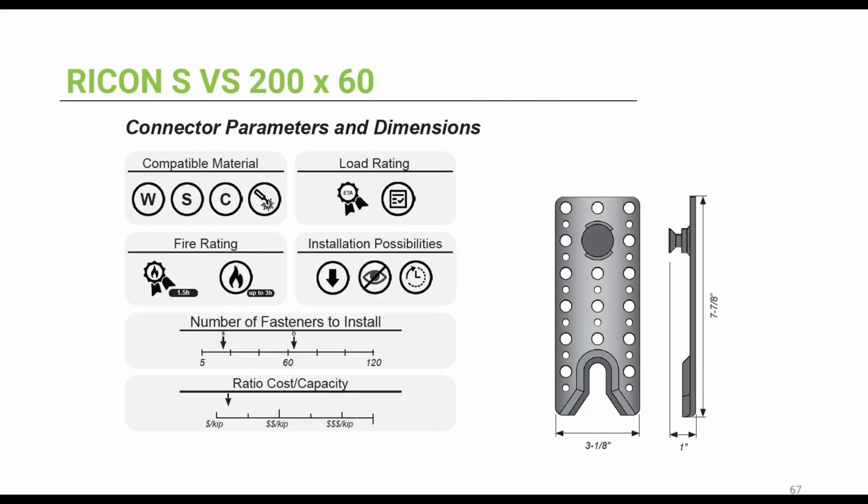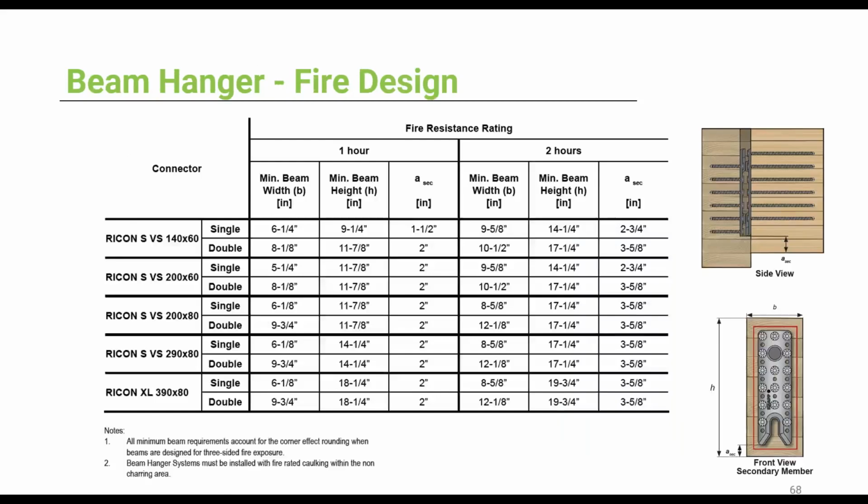And these connectors are tested and included in the exemption from that clause 4.5.1 in the TR10 we mentioned. So if you look, you'll see, oh, it's actually certified fire rated. So perfect. The fire design section of the guide is pretty simple.